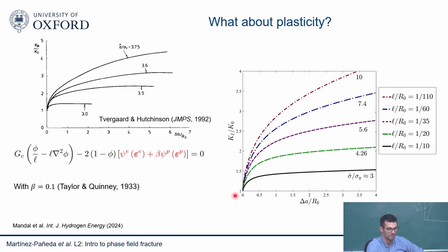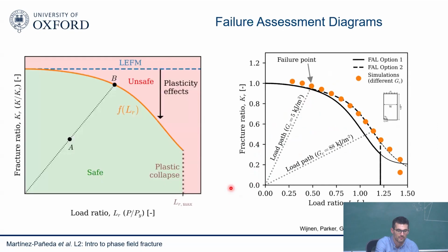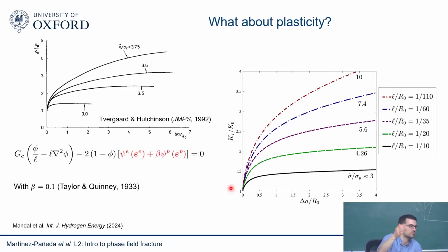Cracking starts always at the same place. You know your fracture toughness. So the only thing that you don't know is how much plastic dissipation you have. And that will depend, of course, on your yield stress, your strain hardening exponent, but those things you know from a uniaxial stress strain curve, and your local fracture toughness, which you can calibrate with this. So that's another option. And then you know that you're dissipating the right amount of plastic work. In this case, this is some sort of a fracture process zone length. It's a normalization, fracture process zone length.